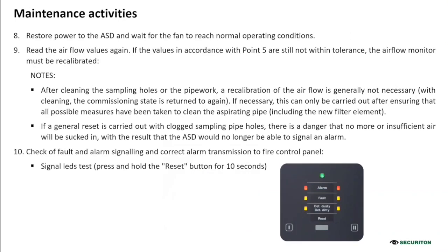Okay, so once you have cleaned up the detection pipe, you can restore the power on the ASDs, and you need to wait for the fan to reach the normal operating condition. That will take at least more or less 5 minutes. Then you read the airflow value again.